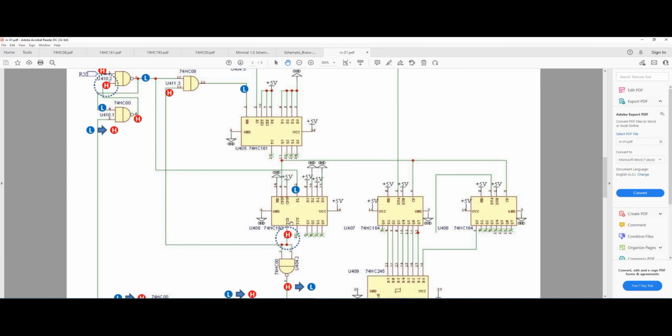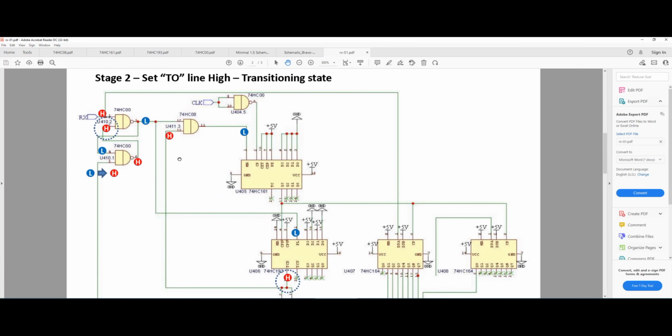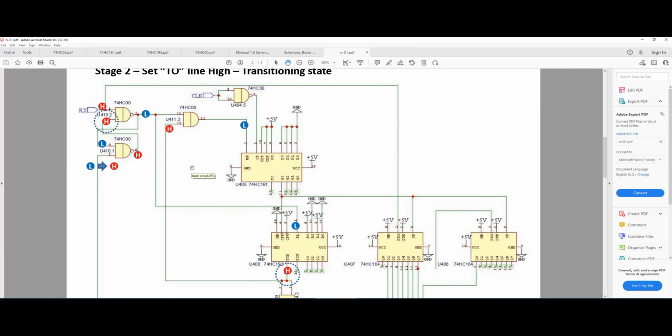And therefore, basically it waits for the clock pulse to arrive and start counting down. However, the TCD will immediately be high. Therefore, that TCD, as you can see, comes back here, and now we have a high signal. At this stage, the circuit will be kind of frozen, and basically two major changes happened here. One, we are latching a high signal here, right? And also, we are setting that pin to high. But at this point, nothing else is going to happen.